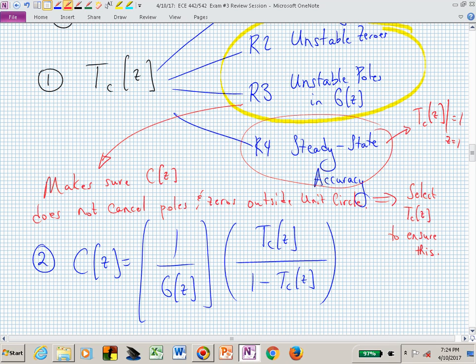If you want even more, if you want certain steady state error due to a ramp input, then you have to worry about the velocity gain constant, which I think we've included in earlier notes, but just in passing. That's requiring a few more steps in the process, but that's what restriction 4 is concerned with, the steady state accuracy.